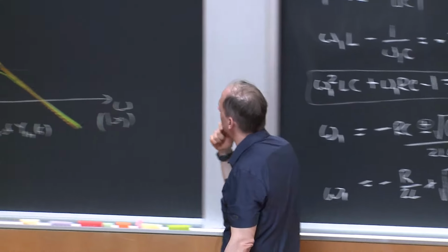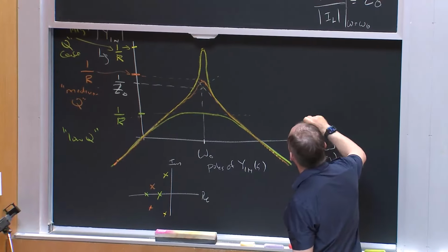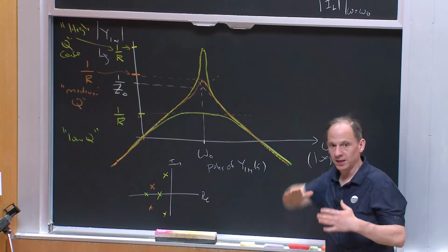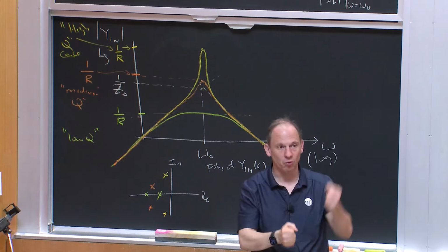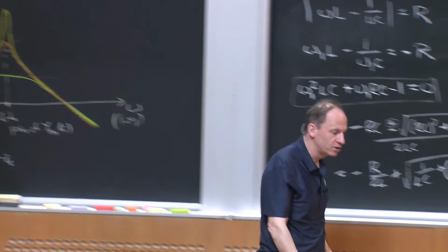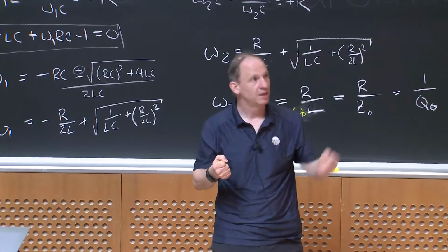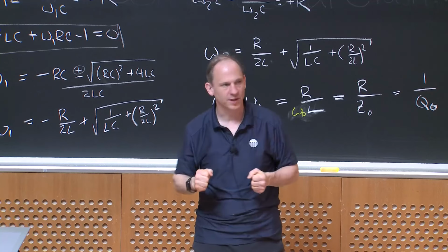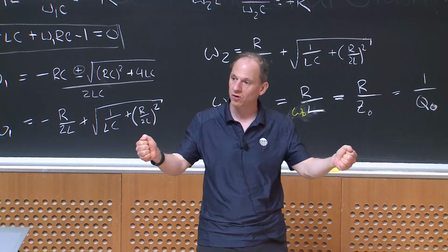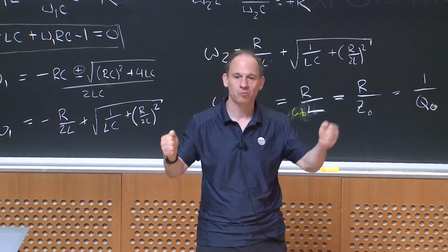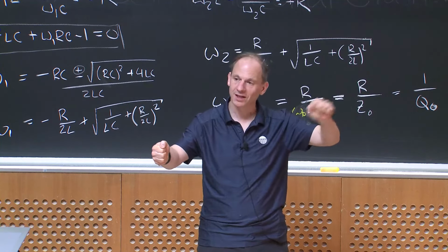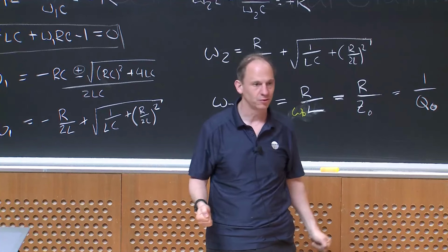Okay, why might I want the peaking? Because what we said was, if I work it out, the more peaky it is, the higher the voltage stress on that capacitor, the more voltage I'm putting across the capacitor and the inductor. And in some cases, we can use that to get voltage gain. In fact, if I were thinking about a lamp ballast, it's not a series network in that case. It's a parallel network. But I might actually use that. So if you want to break over a fluorescent lamp ballast, it's more or less an open circuit. You want to break down the gases, the voltage of the gases, to make it strike. You can use the resonant gain of your network to get voltages that are much bigger than your drive voltage.